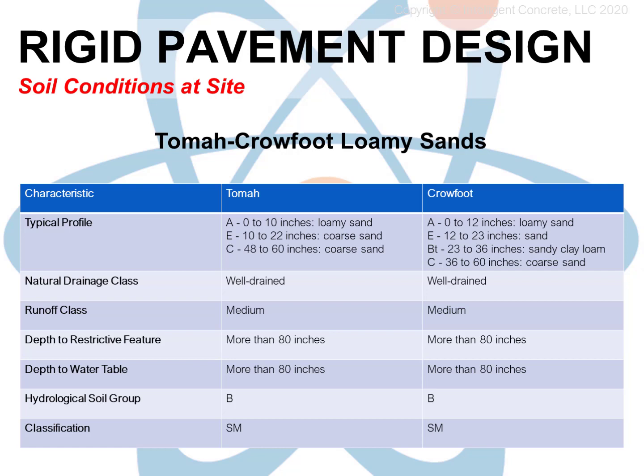Oddly enough, the USGS and USDA, who provide a great deal of the available online soil information, use terms like sandy loam and clay loams and silt loams, but we as engineers like to use terms such as sand or silty sand or clayey sand, which are from the Unified Classification System, which is another government project through the ASTM, or American Society of Testing and Materials.